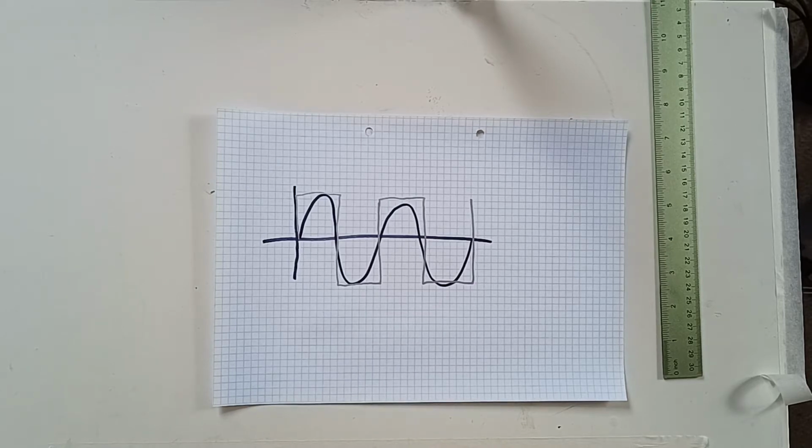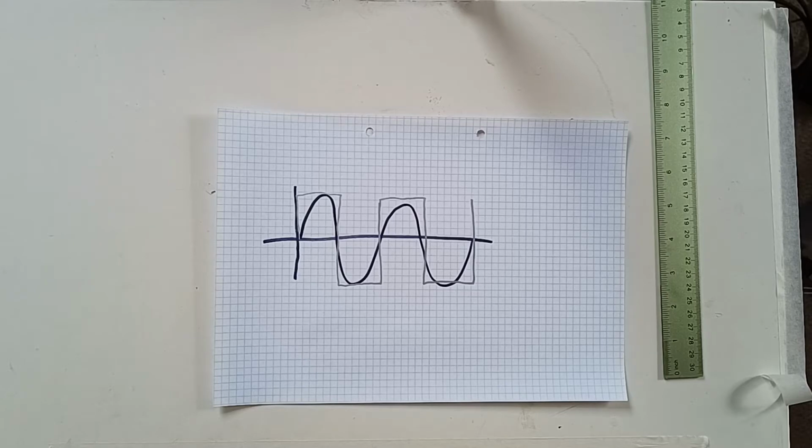So there are two main types of synthesis. There is subtractive synthesis, where you start with a very textured signal, like the square wave there, and you remove different frequencies from it to get the underlying sound that you want. The other form is additive synthesis, which mostly uses frequency modulation, where you mix different frequencies together to produce your sound and then move them all around to different pitches when you need them.